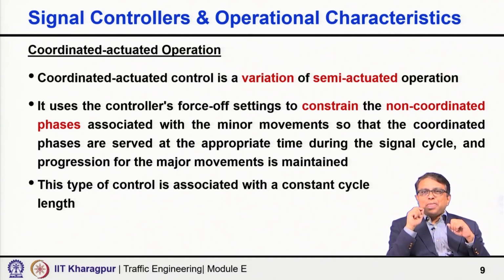That means, one thing is very important here: the cycle length will not be different over time, the cycle length will be fixed, and within the cycle length the minimum green time given for the major movement is also fixed. Okay.